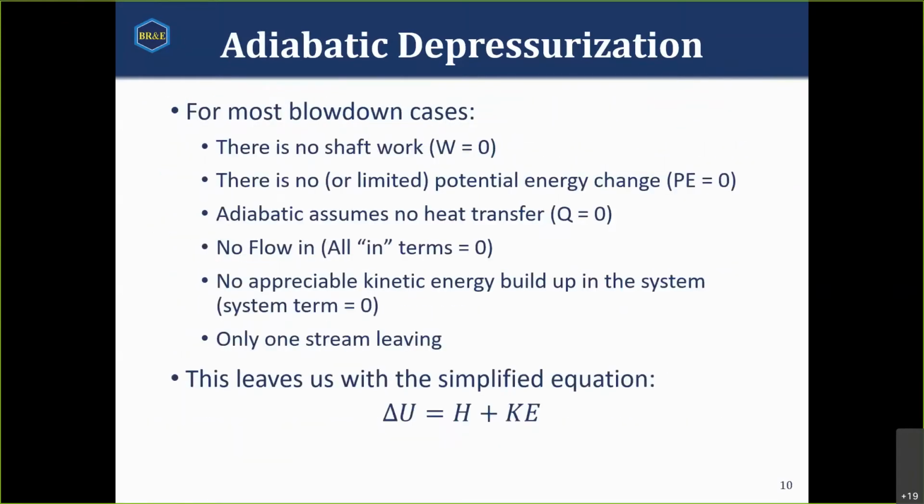Well, what about this kinetic energy term? I have a system that is, for all practical purposes, stagnant. I'm not going to look at the molecular level. Of course, the molecules are moving very fast. It has to do with temperature and entropy. We're going to ignore that. We're saying the system itself isn't moving. But once I open a valve, all of a sudden I go from zero kinetic energy to some kinetic energy. Isn't that important? Do we need to worry about it? So let's look at that. Let's examine this kinetic energy term.